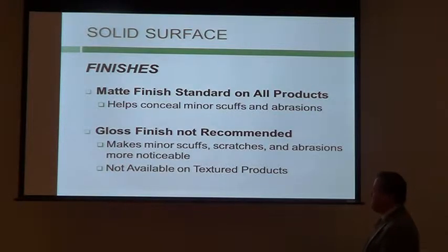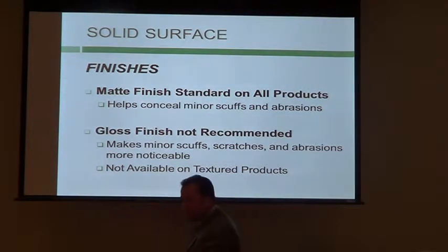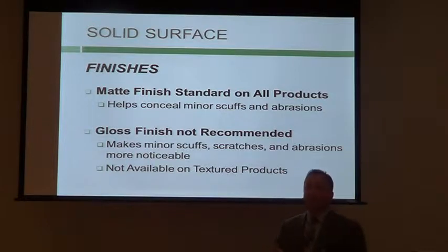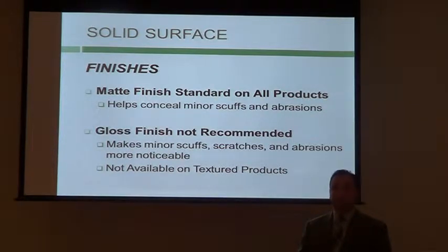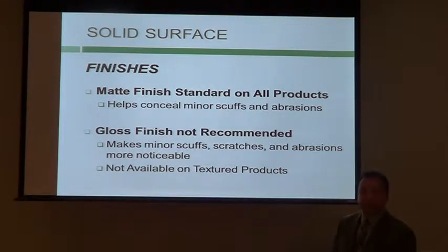And why is it not available on textured surfaces? If you think for a moment about the wood analogy, if I have a texture, which all shower bases are going to have a built-in texture, for me to lift the sheen of my wood, the hickory and the maple analogy, I use a finer and finer grit of sandpaper to lift the luster, make it really smooth, apply my finish, lifts that luster. Well, I can't sand down the texture, because that would defeat the coefficient of friction that we're looking for in a shower. So I really don't want to sand it to create a glossy finish, because I would then be sanding away the benefit of the texture.